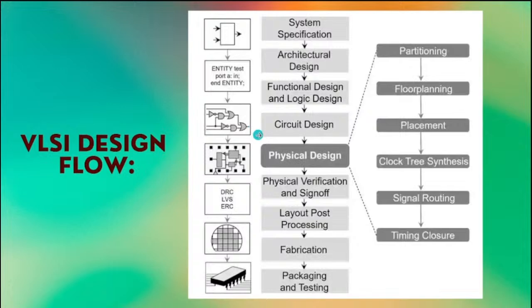In front end engineering we have two roles, the RTL engineer and the verification engineer. The RTL engineer will write the design code for the required specification, and the verification engineer will write the SystemVerilog test bench or UVM test bench to verify the RTL design. So we have to write the design code, and then we have to write the test bench code. We have to make sure all our test cases pass. If there is any error, any bug, it will be a very huge loss for our company.